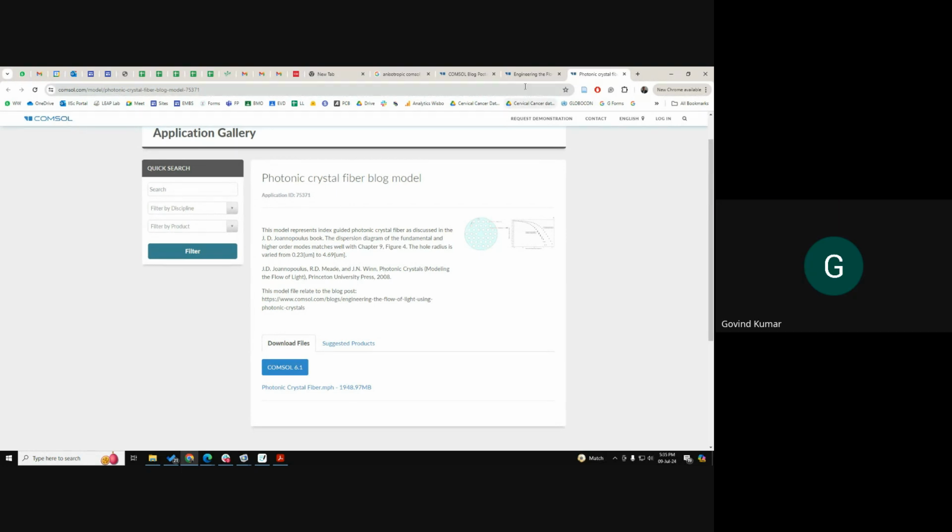Sorry. So, these modes are bound modes that propagate inside the core, and a few will go into the cladding, which is called a leaky mode. Then there is a radiation mode, like we also see in photonic crystals, where light is going above the air line; that is a radiation mode. So in fiber also, I read about radiation modes in a few papers. How can we identify this?